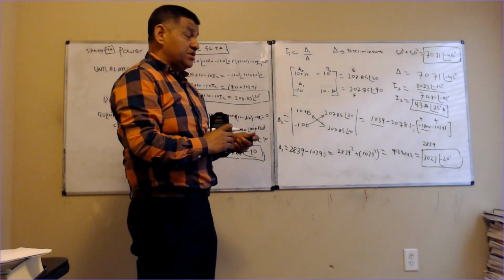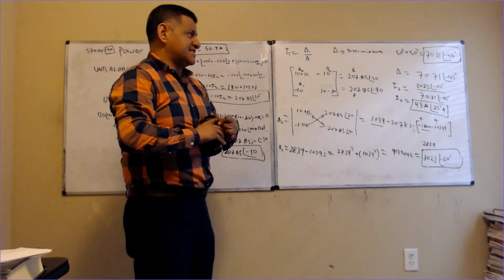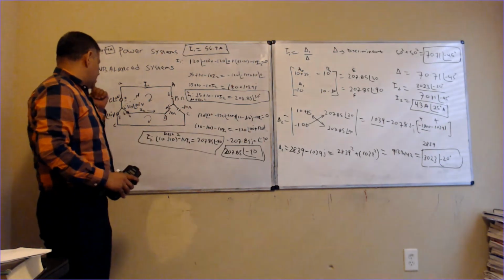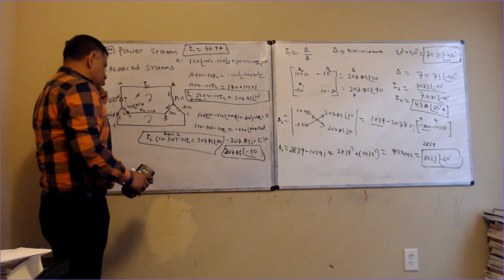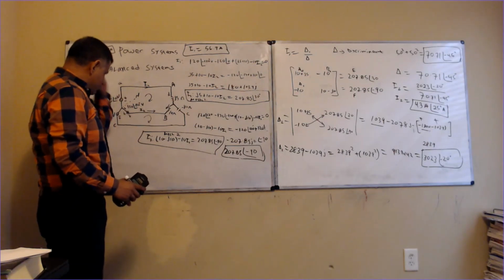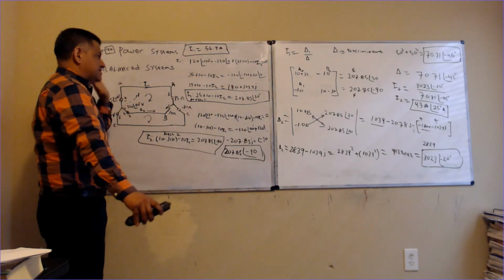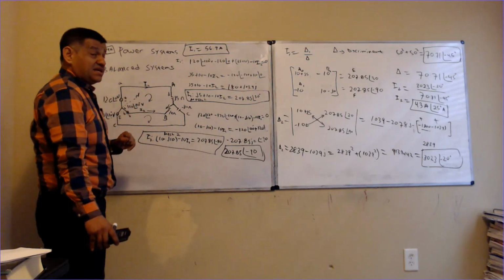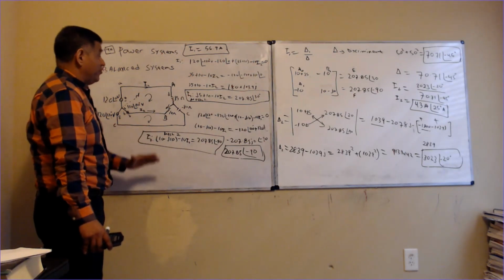If there is a load, you don't want to touch the neutral, because if the current is imbalanced, that current will go back to the source. If you touch the neutral and grab onto something conductive, you will be in deep trouble. So be careful with electricity.